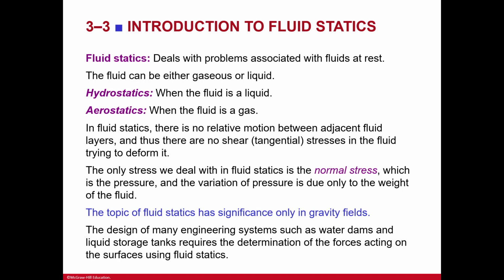and thus there's no shear or tangential stresses in the fluid trying to deform it. The only stress that you do deal with in fluid statics is normal stress, which is the pressure. And the variation of pressure is due to only the weight of the fluid. And you do have that, right?